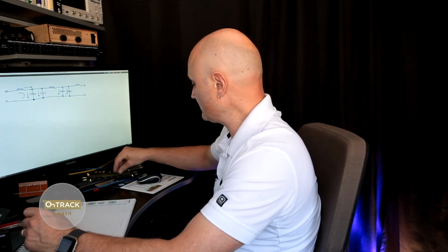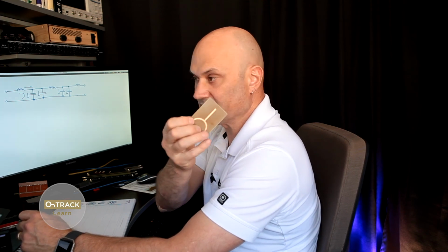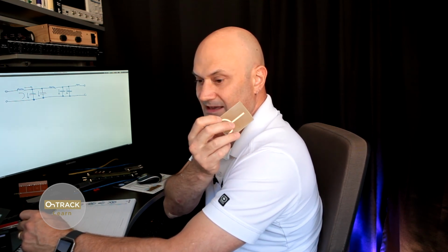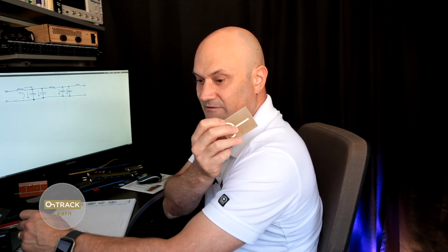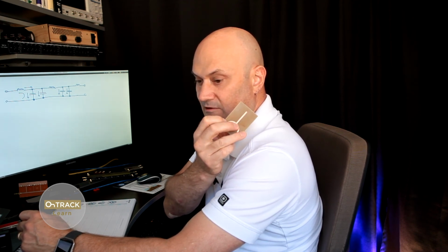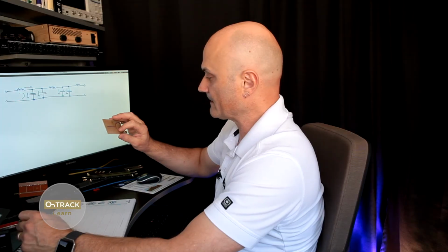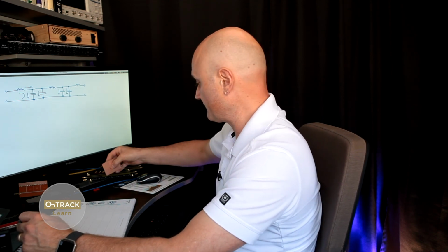And how do you calculate these? Well, you can use some of those transforms I showed earlier. And here's a few more that you can use, because there's always some inductance, just like we looked at with this transmission line segment. It's an open circuit, so it appears like a short at the center frequency, where that's a quarter wavelength long, but then it becomes an open again at higher frequencies, and then at a multiple of a quarter wavelength, it becomes a short again, and so on. And so you can see there's this repetitive nature to the frequency response.